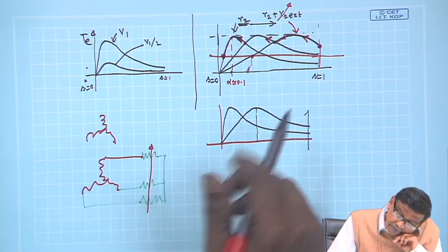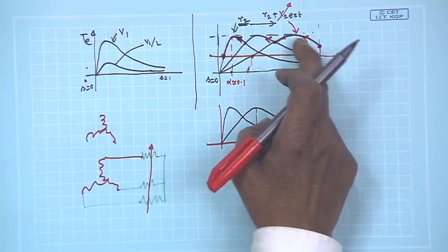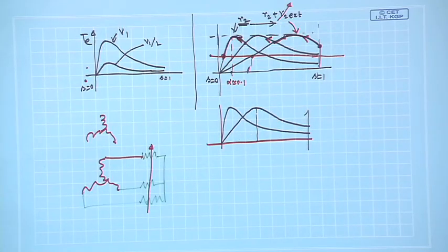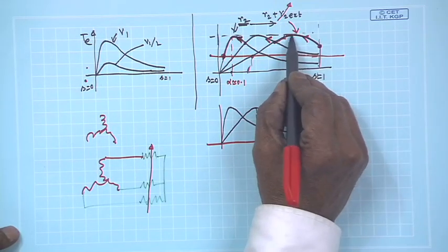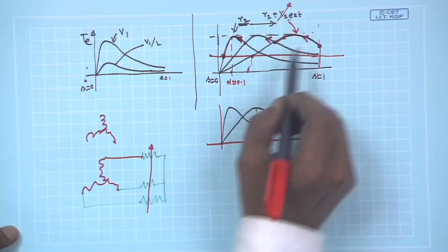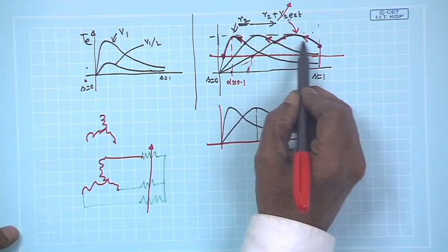That is, you should always think that this external resistance is to be cut out, and how the operating point will move. You decrease this resistance, and there are some torque slip characteristics based on the R2 external that exists.